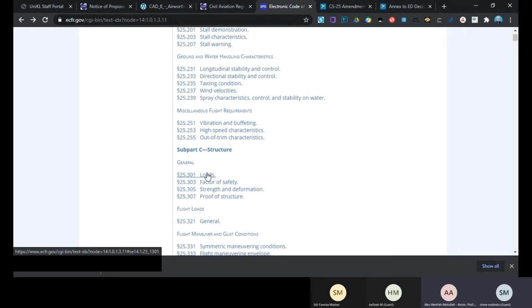Either, like I said again, we set it as what we wish. For example, A320 is 120 ton. It was set as such. And then factor of safety. All the structure must meet the minimum factor of safety in designing for that load. So the authority requires 1.5. That means 50%.